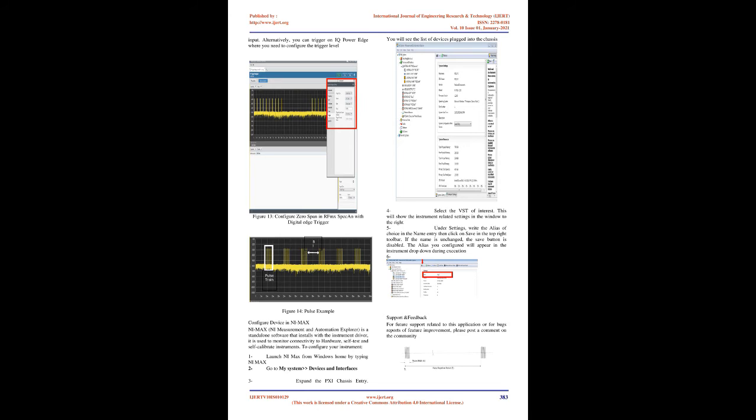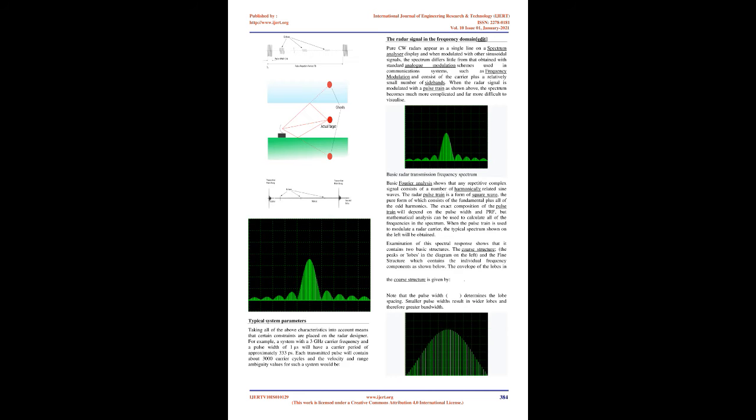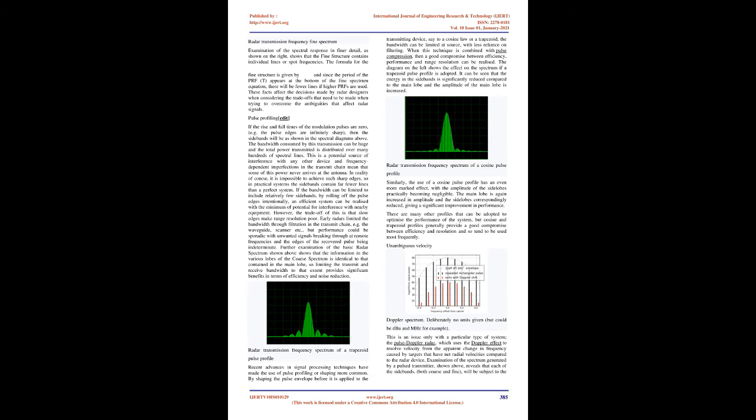A special class of binary codes is the optimum, or Barker, codes. They are optimum in the sense that they provide low side lobes, which are all of equal magnitude. Only a small number of these optimum codes exist. They are shown on the beside table. A computer-based study searched for Barker codes up to 6,000, and obtained only 13 as the maximum value. It will be noted that there are none greater than 13, which implies a maximum compression ratio of 13, which is rather low.